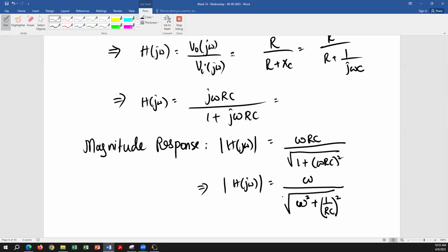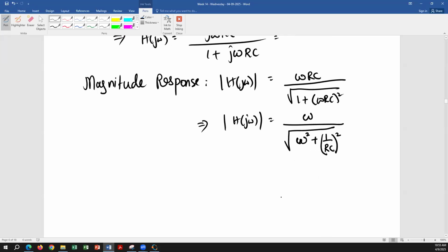So that's going to give you, when we eliminate, of course, the square, you're going to have a square root of 2 times 1 over RC in the denominator at omega equal to 1 over RC. And in the numerator, we'll have 1 over RC. So you're going to be left with 1 over square root of 2 at omega equal to 1 over RC.